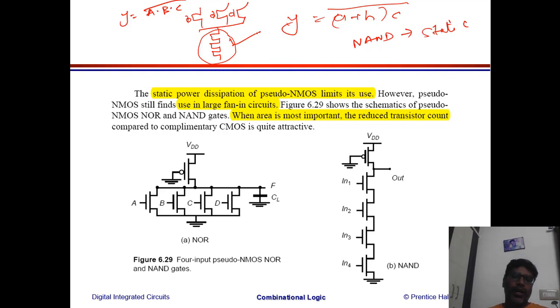Why? Because the NMOS speed is around 2.5 times or even 3 times higher than that of the PMOS. So if you stack an NMOS, it's actually the series combination of all these 3 that adds up together to form the delay. So if you keep on stacking an NMOS, that is better compared to a PMOS.